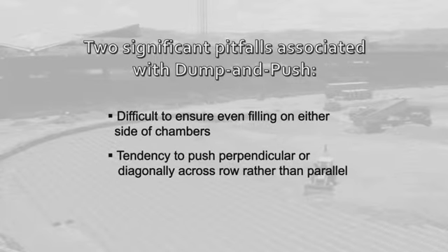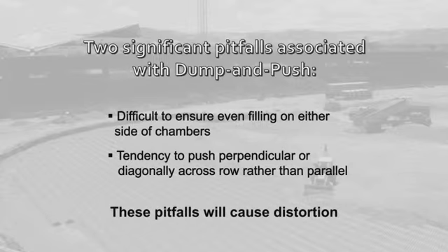Two significant pitfalls associated with dump and push are, first, that it's very difficult to ensure even filling of embedment stone on either side of the dozer blade, causing chambers on either side of the dozer to distort. And secondly, that the tendency of the operator is to push perpendicular or diagonally across the rows as the backfilling proceeds along the bed, rather than always pushing parallel from the starting edge of the bed all the way to the leading edge of the fill. Pushing perpendicular to the chamber rows with insufficient cover will cause distortion of chambers. Therefore, the dump and push method is not an acceptable method to backfill chambers.